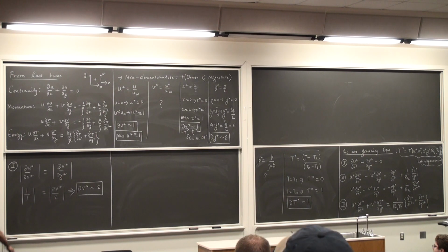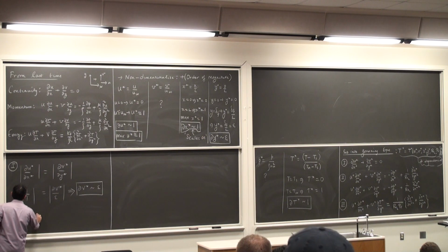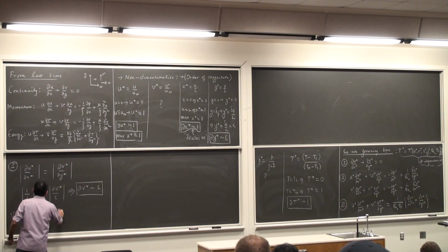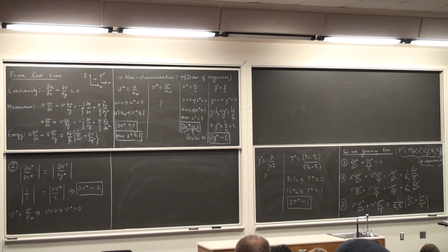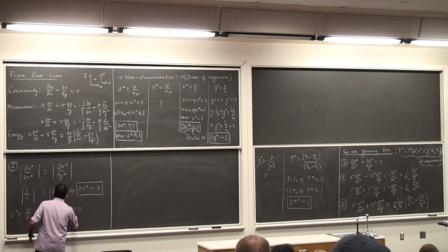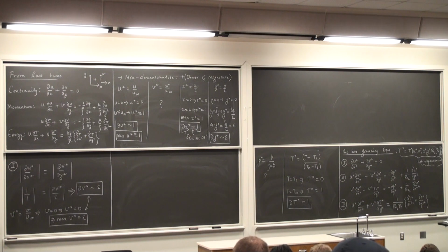And if I look at v star, which is v by u infinity, I obviously know that if dv star scales as epsilon and the initial value of v star is 0, so at v is equal to 0, v star is equal to 0, I know that the range of dv star is epsilon, so that the maximum value of v star is epsilon. This is because dv star is v star max minus v star min.